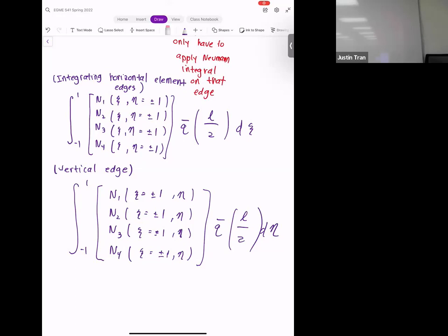It would be incorrect to say that weak form is a different problem than strong form, which people might write because they look so different. One has no integrals, the other one does. But they're the same problem. If you solve them exactly, which is the key, you end up with the same answer. The way we do it in class, we end up with different answers sometimes because we don't solve them exactly. The strong form we solve exactly, but the weak form we solve approximately. That's the difference. But they express the exact same problem. And if you find an approximate solution to the strong form, you're going to get the same function.